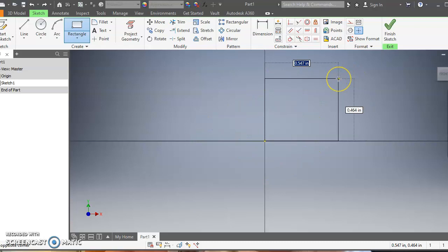Okay, so if I want to make a square before I can make a cube, because obviously a square is 2-dimensional, and make sure that my length and my width are the same. So one way you could do that is you could try to take your cursor and drag it so that those 2 numbers are the same, but that's a big waste of time. Okay, a better way to do it would be to actually type in your dimensions.